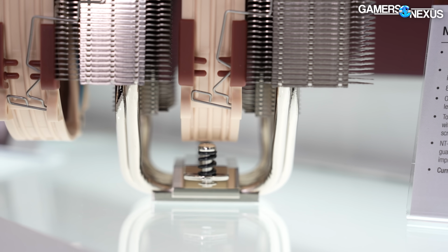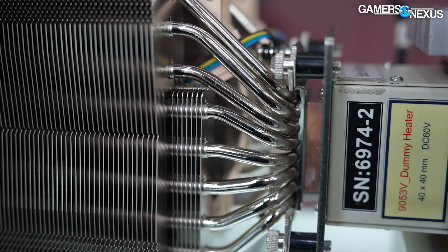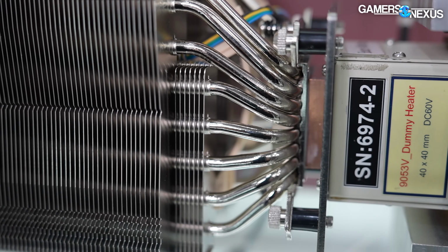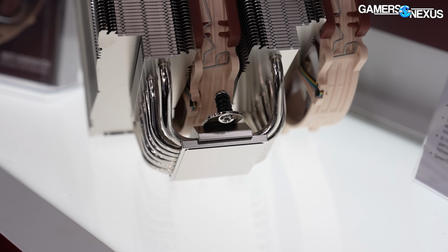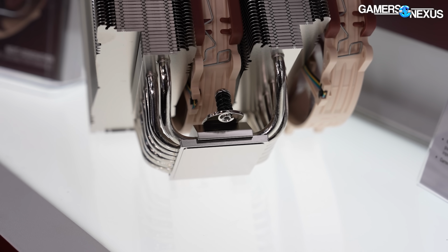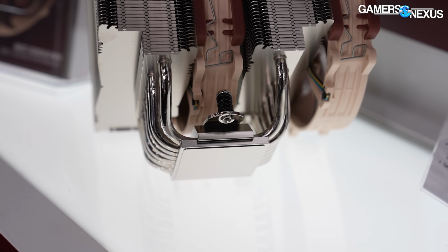And then since the heat pipes are converging towards the base once we go further down, we need to have another fin tooling that basically has a wider slot opening for the angled heat pipe to pass through, versus the straight ones can still attach to the fin and be soldered to the fin. And that's the reason why we have different fin types there. So it's purely mechanical. Right.